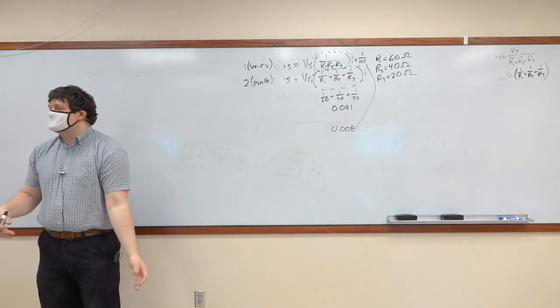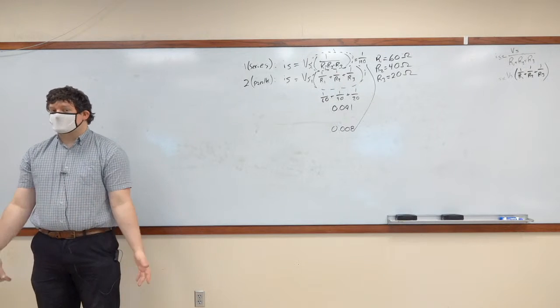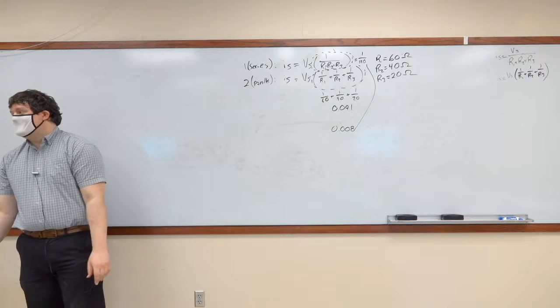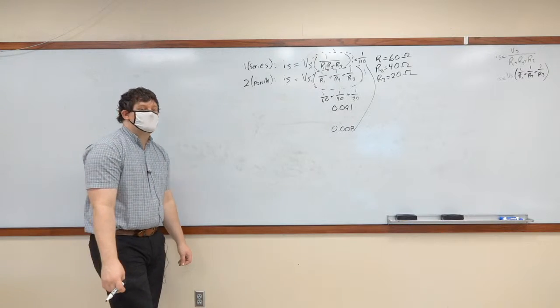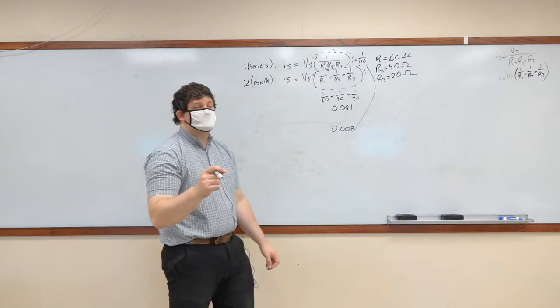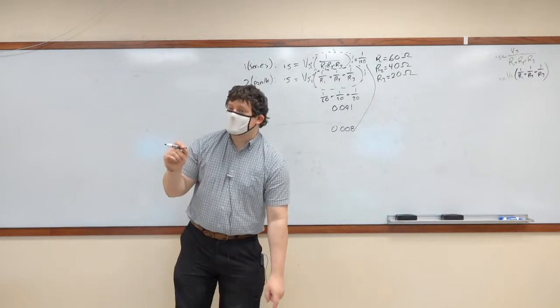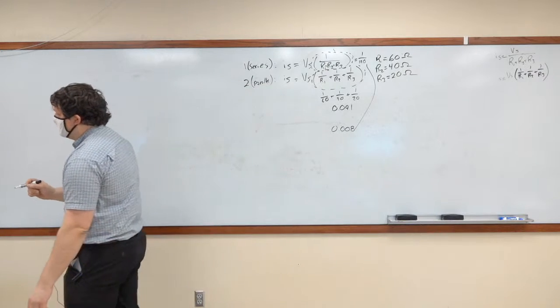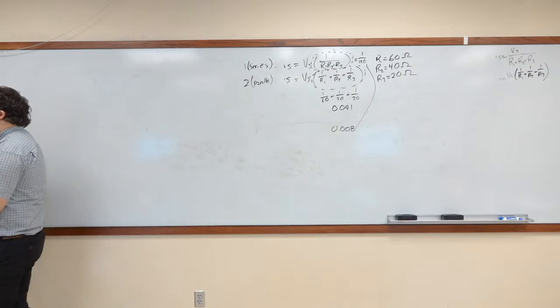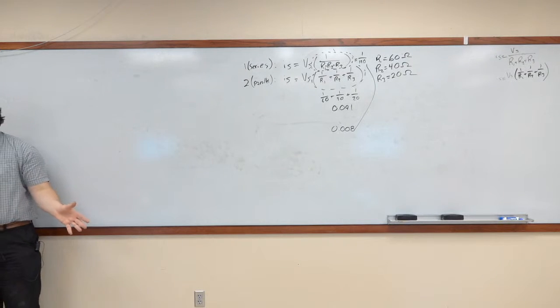And why are these numbers so different? Because series and parallel are different configurations, okay? If you combine components in parallel, the power consumption for the entire circuit will be higher. Why? Because in a voltage source, they're all going to be at the same voltage.